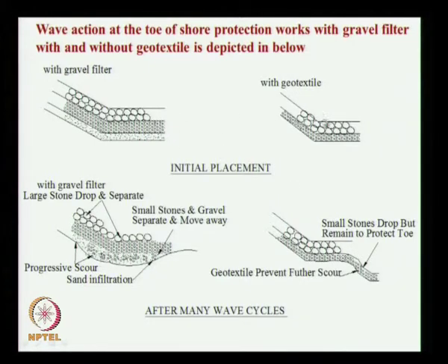The top figure is initial placement, both look alike, only thing is here we have a geotextile filter. The bottom after many wave cycles. So what you are seeing is this bed material is mixed with the stones which are coming here, whereas here you are seeing the bed material.